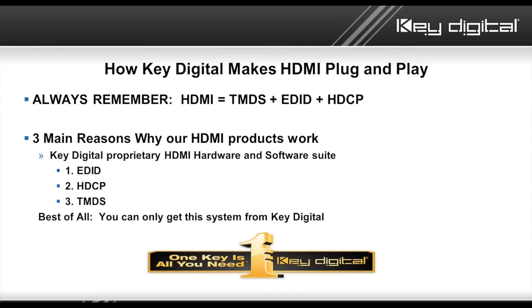For going on 10 years now, we've been developing HDMI switching and distribution products and extension products that have always recognized that HDMI is not just a video and audio signal. The video and audio is one of the 3 layers, but the other 2, EDID and HDCP, are what complete that formula. Now, TMDS stands for Transition Minimized Differential Signal. Don't worry, you don't have to get the pen and paper out on this. What it means is the video and audio layer of your HDMI signal.